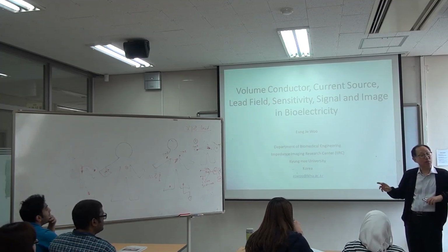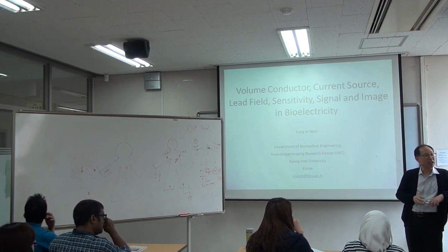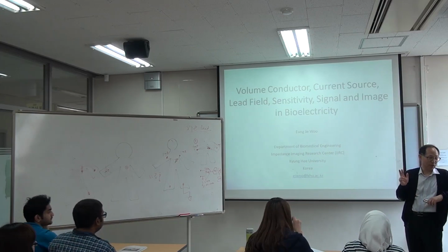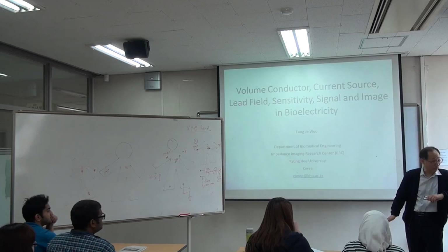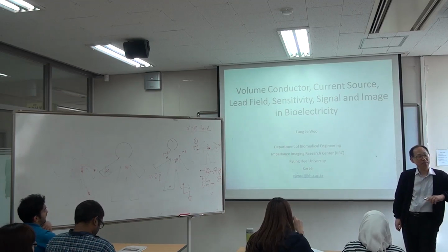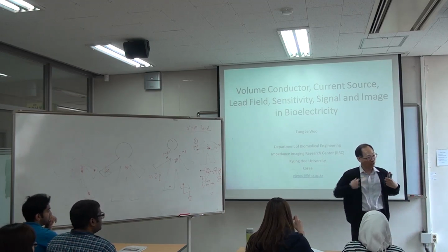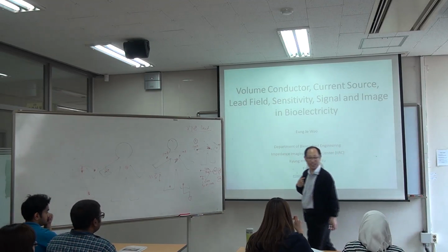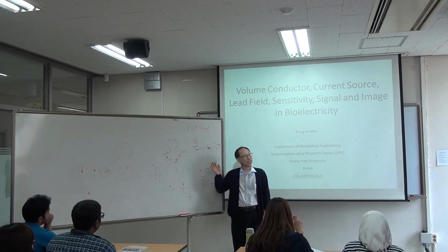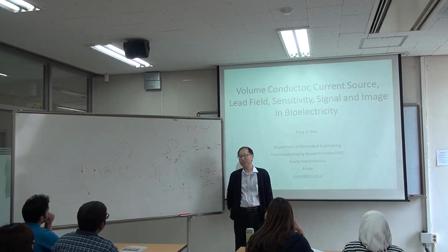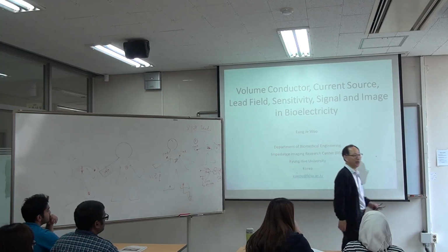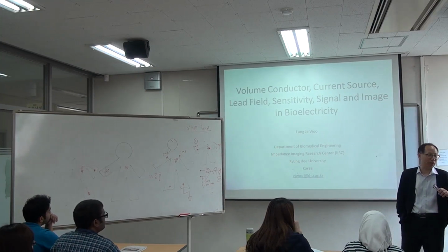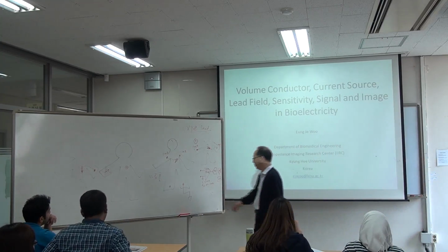For monitoring purposes, for the monitoring of your heart beating, they just use 3 electrodes. One here, a second one here, and the third one, which is for ground, anywhere on the body. Anywhere. Doesn't matter. Okay? In that case, they are just measuring the ECG signal between these two points. Any questions? This is something you have to test yourself to find out whether you understood the lead field theory or not.